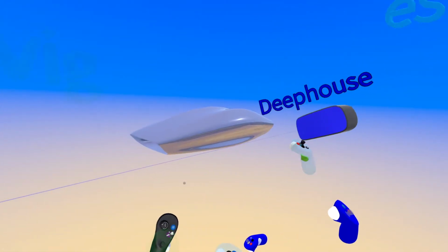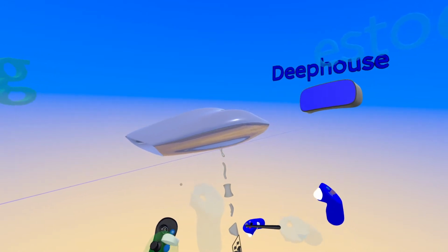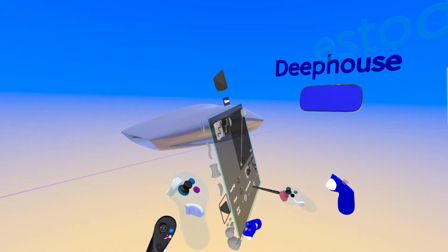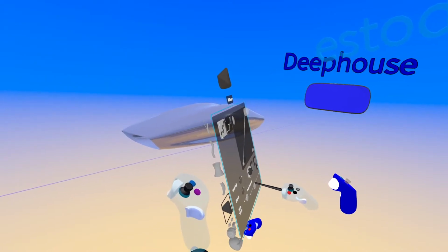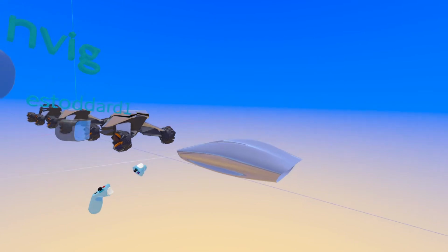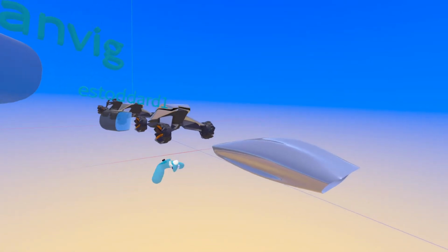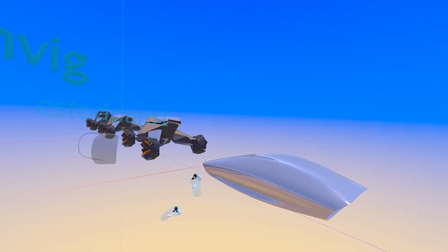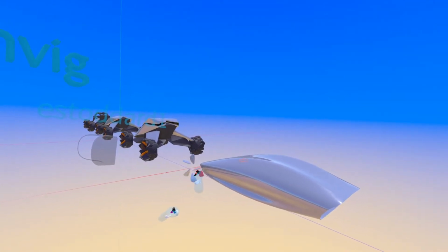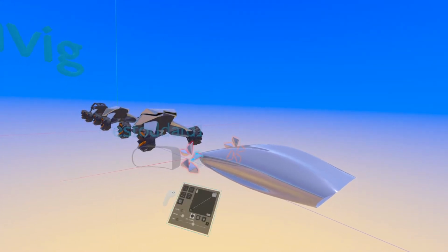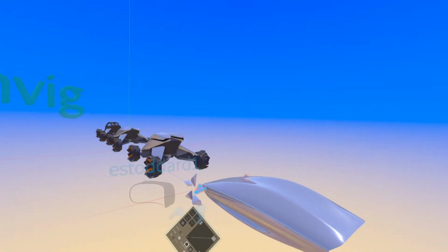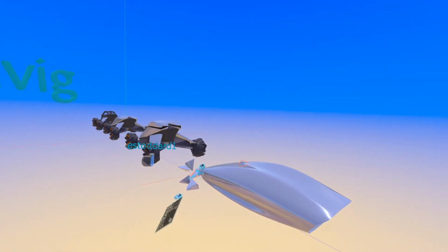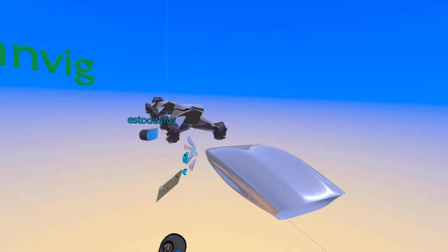So what I'll do is I'll go back in again with the volume tool, turn the polar symmetry on, and let's just start with 5 spokes and see what we get. And let's just start putting some spokes together.